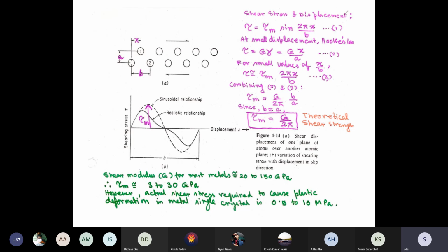But for the time being, you do certain thermal treatment in an alloy, and in that alloy during thermal treatment, a tiny second thermodynamic phase forms. And why they are tiny will be taught later, and if they are very large, it will ruin the properties. That we'll learn in this chapter. So these second phase particles strengthen the material. Whether you see aluminium pots and pans at home or an aluminium body of a fighter plane or a commercial jet engine, say jet planes, they are aluminium alloys and they have fine precipitates.